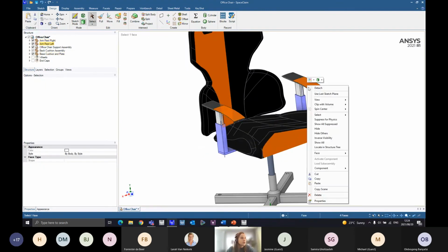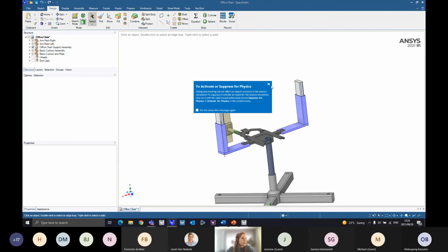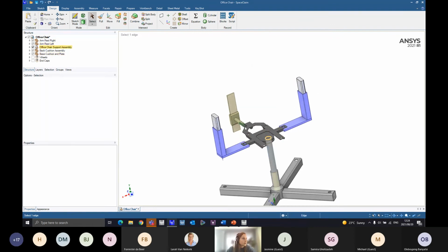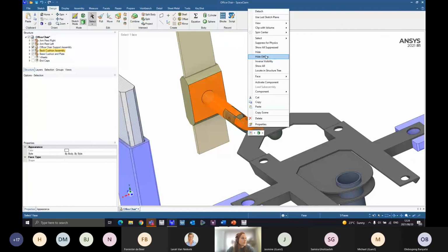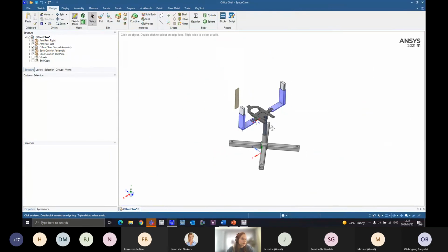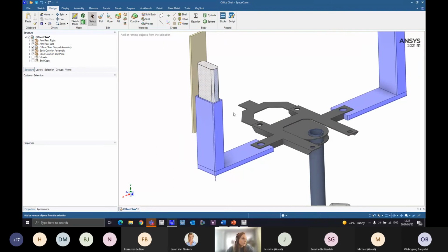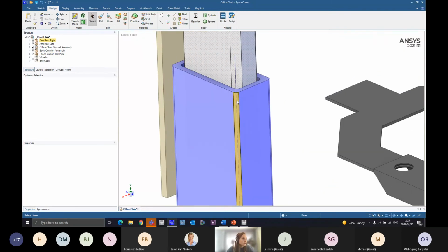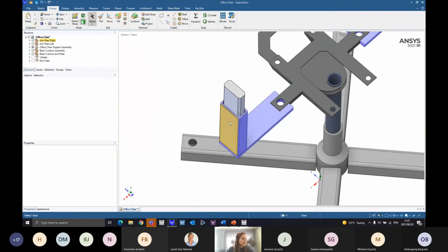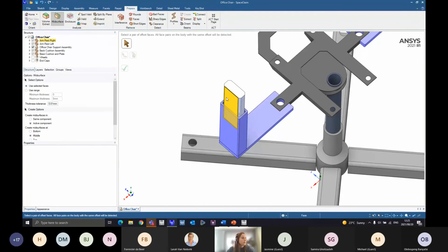Okay, so let me start by just adding some of my solid bodies to make it a bit easier. I'm gonna hide these as well. Okay, cool. Let me start with my mid-surfacing. So before I start, as you can see, there are some rounds on this body over here. This is not a problem. You can still probably mid-surface this body, as I will show you now.